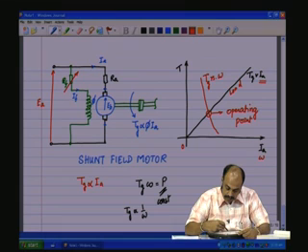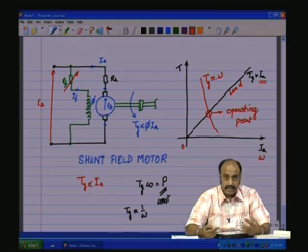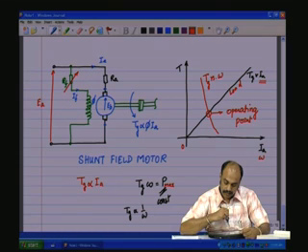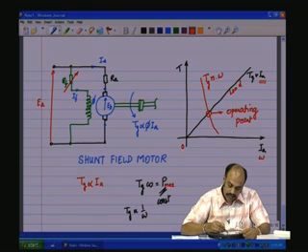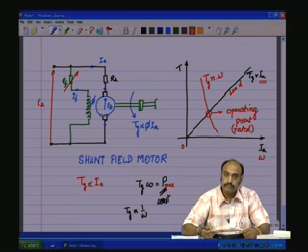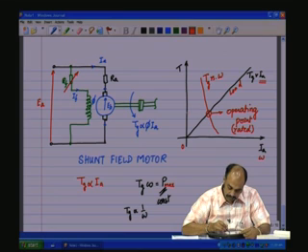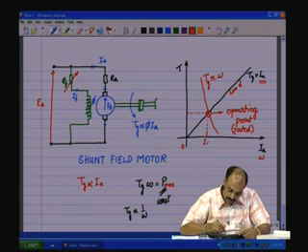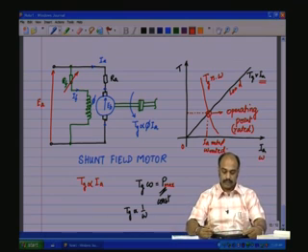And because the power is constant, meaning we are at, let us say, the maximum power P max, let it be constant at P max, then this would indicate maximum or rated load, this particular operating point. So, the torque at rated load and rated speed or the nominal speed. So, that would be your Ia rated, omega rated in radians per second.